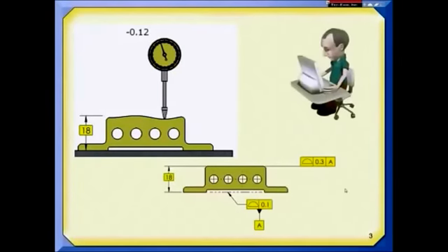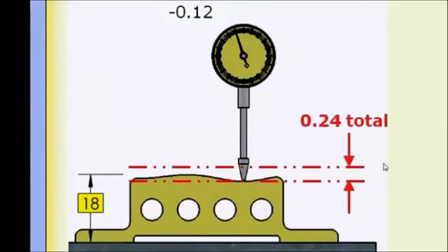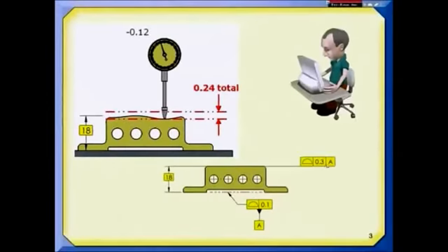Since the tolerance zone has to be centered, if I want to compare the deviation in the part to the stated value, in other words, an apples-to-apples comparison, I would double the largest deviation to determine the width of a tolerance zone needed for this part to be acceptable. If that value is less than the value stated in the feature control frame, then I have a part that passed inspection.